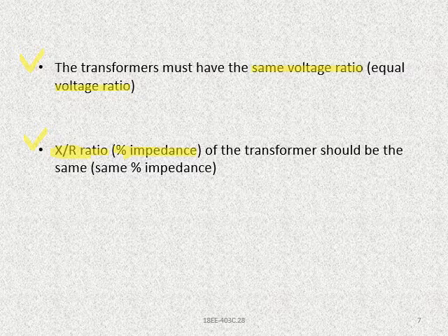Once again, we'll just analyze the points. First one is voltage and frequency should be same. Second one is polarity should be same, like plus and minus should be same.